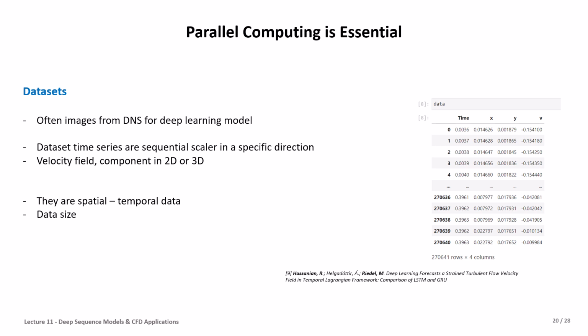and it's different from some data that could be obtained from the numerical approach, because in the numerical approach we have some limits. Maybe we cannot study some effects like gravity because of the complexity and the computation, but here the real world data is available with all effective parameters. Because turbulent flow is a three-dimensional phenomenon, if you are doing a simulation in only two dimensions, it doesn't cover all the information of the turbulent flow. It is necessary to make a simulation in three dimensions to have full information. Therefore, in the experiment, we have all the required information of the turbulent flow.